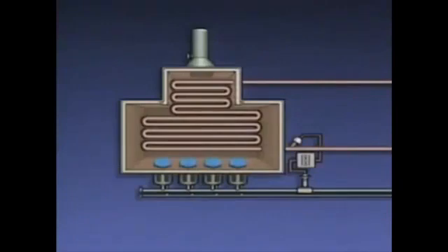For many furnaces, both the process fluid outlet temperature and the process fluid flow rate are controlled automatically. You should know how your furnace's control systems work so you can monitor the way they're controlling the furnace. Let's look at a typical example. This system controls the process fluid outlet temperature by adjusting fuel flow to the burners.